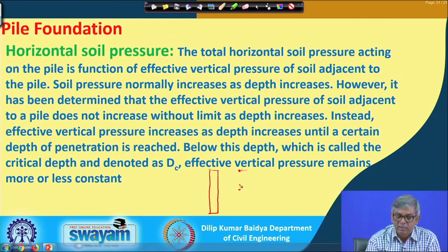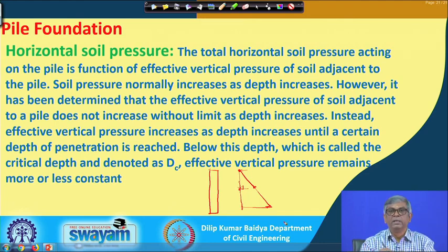At this step the vertical pressure will be some value, and the horizontal pressure is also bigger than 0. Maybe suppose the value is somewhere here. This will definitely vary linearly, gamma times h, it is linear. So, it will go from this to this, and if I now reach here, the value will be something like this. So, the lateral pressure is continuously increasing.